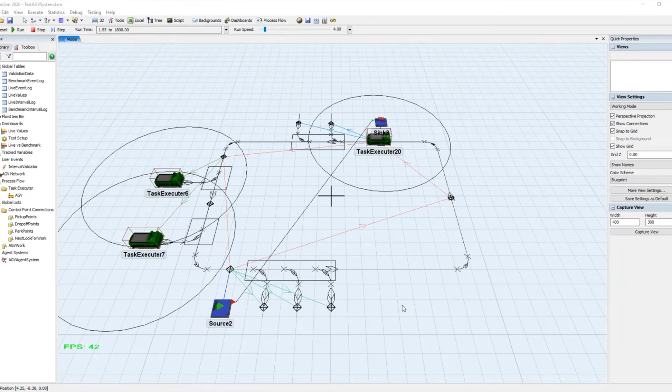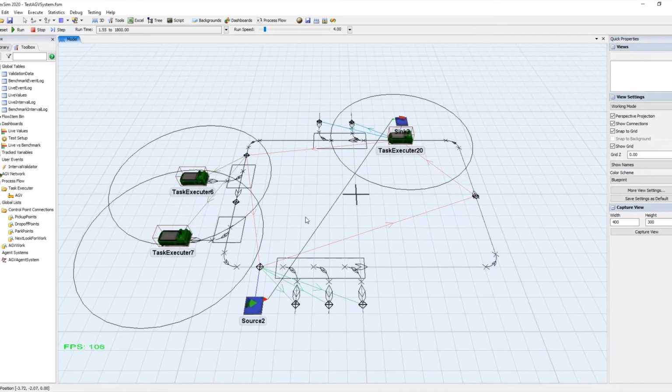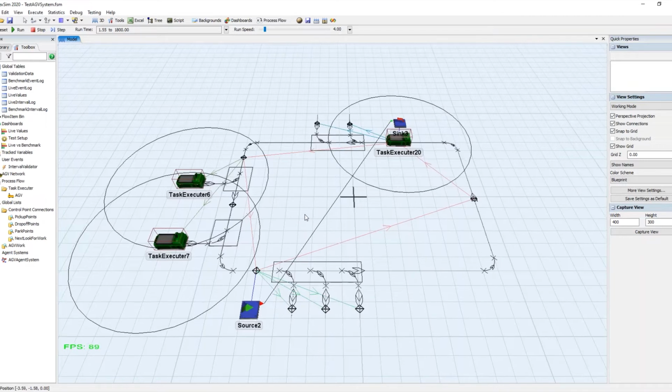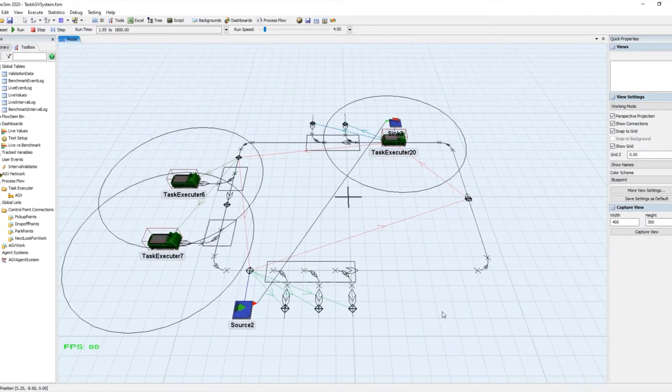Here's another example of using a proximity detection system. This is specifically for an AGV system. One of our German distributors requested a specific type of behavior that was not part of the standard accumulation behavior in AGVs. What he wanted was a two-speed system where if AGVs don't have anybody near them, then they will go their standard speed. And if somebody comes within a small proximity, then they will decrease their speed down to a slow speed. Then if they get really close, they'll actually stop. So it's two speeds and then stop.